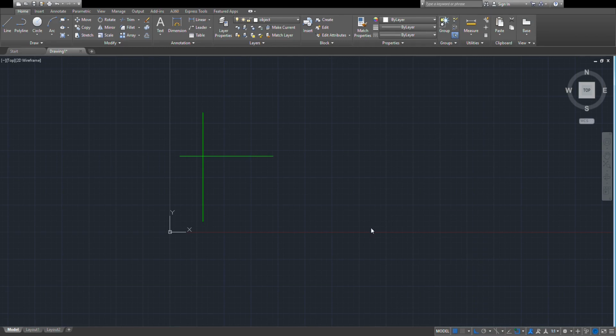You just click at the intersection, and there will be an X appearing on your screen, which means you are pointing to the intersection of these lines. So we are going to specify our center point at this intersection. Just click at this intersection, and they are asking us the radius, but in our drawing it is written as diameter, so we don't want to have any mistakes.